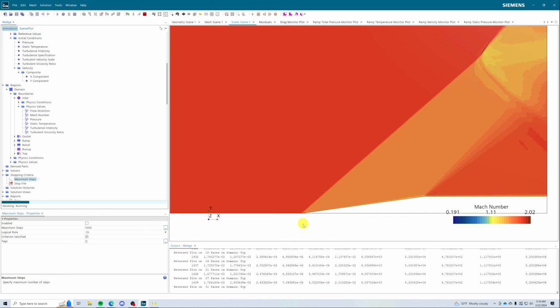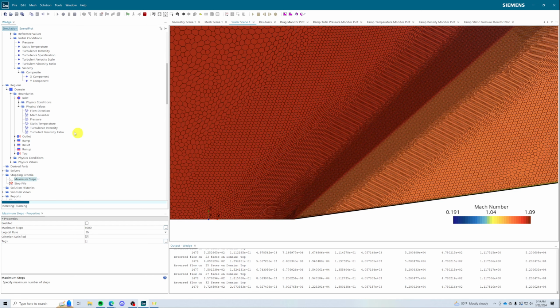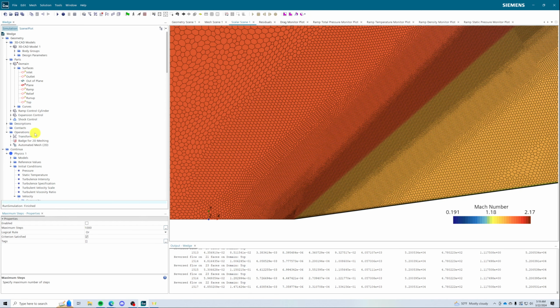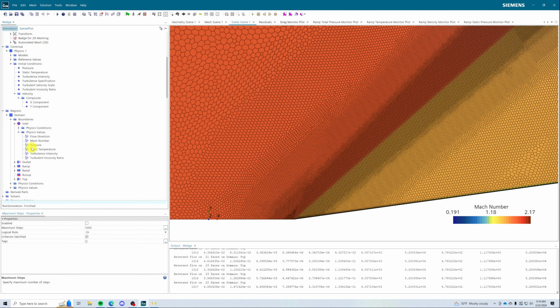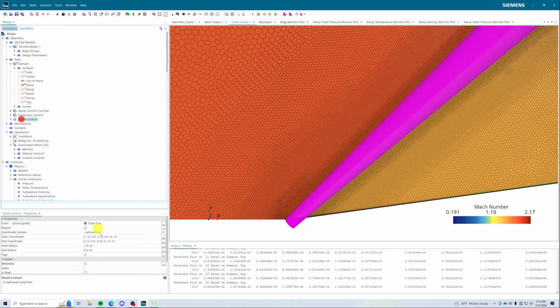So honestly, it doesn't look like we needed this cone to be as big as it is. We can make this run a little bit faster, or honestly, probably a lot faster, by editing the properties of this cone. So instead of 1 centimeter leading edge, we're going to make this like 0.5. Instead of 6, we're going to make this like 2 for that.